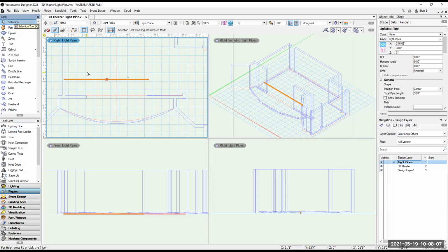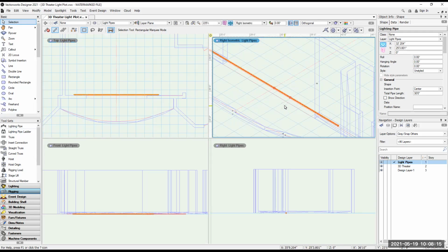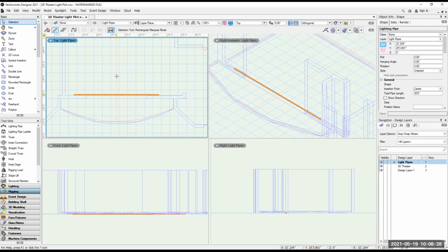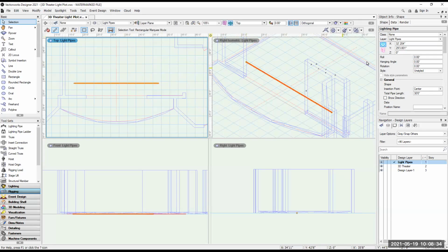Anyway, I'm going to move this pipe to the right spot. Yeah, computers are very frustrating. But as you can see, this pipe is right on the floor. When you install this thing, it's at 0 inches off the ground. If I wanted to move said pipe, it's the same process as before. I just drag the pipe up, tab, I'm going to put it at 4 feet from the proscenium, bang, and now I'm going to want to put it in the air. So now I can change this to 12 feet, 0 inches, and you'll see that the pipe will move in every one of the drawings.